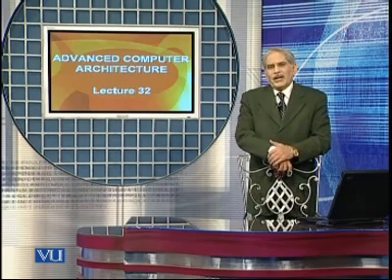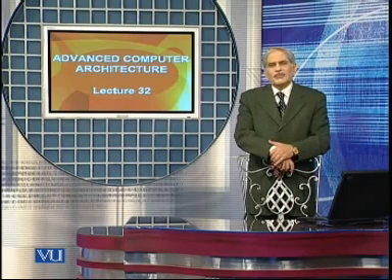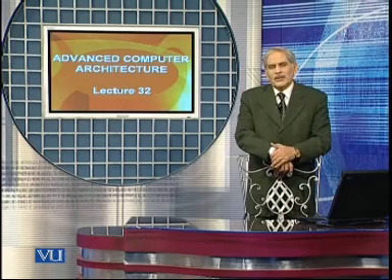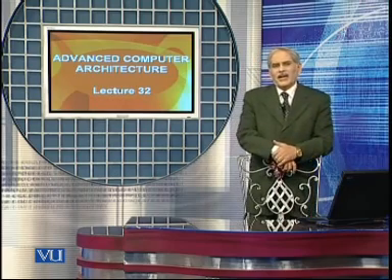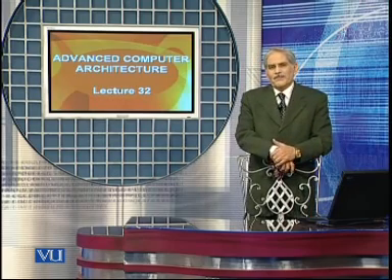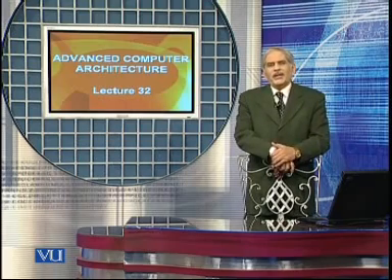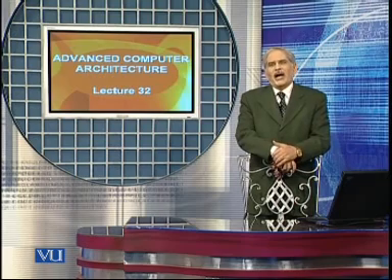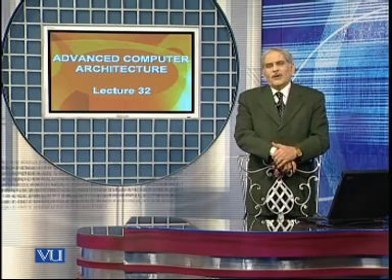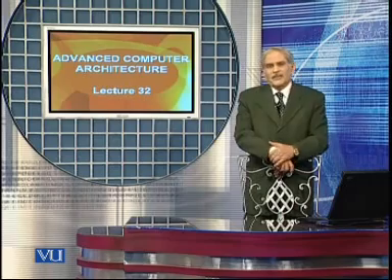This decision is essential to ensure that if memory is being accessed sequentially, for example, when we are processing an array, then by the time you try to read a second word from a bank, the first access has finished.